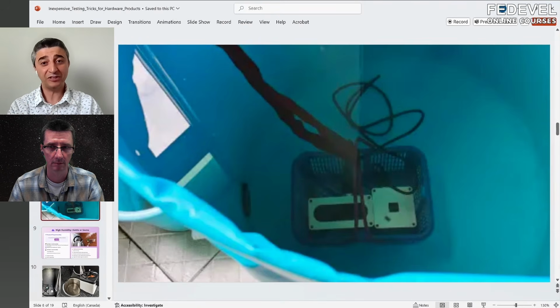So there was still some leakage, and we had to find out it's coming from that location. The solution to this was to have a proper kind of sealing. So we added another kind of gasket to seal that hole. It was an easy thing to me.